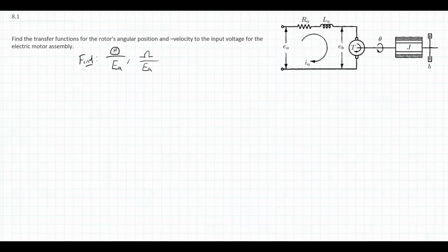So we have these two subsystems that are interfacing at the motor, the electrical system and the mechanical system. So we're going to start by treating them kind of independently and then link them together by that interface they have, the DC motor. And we're going to make some assumptions about the DC motor so that we can solve this problem, that it's going to have a linear relationship, that we know what some of the interface constants are, but we'll get to that in a moment.